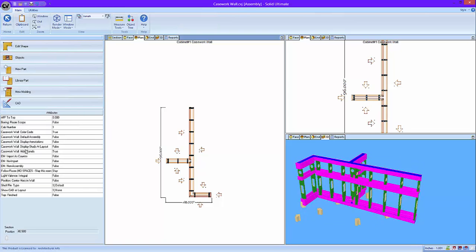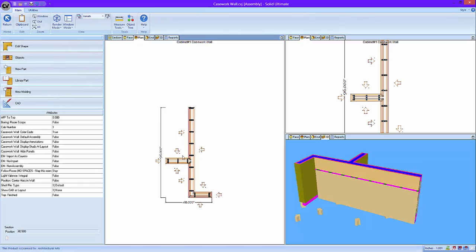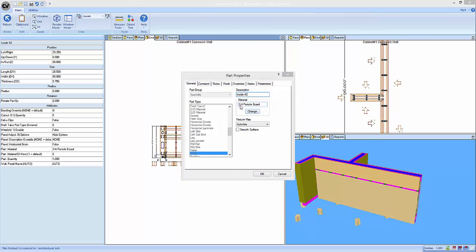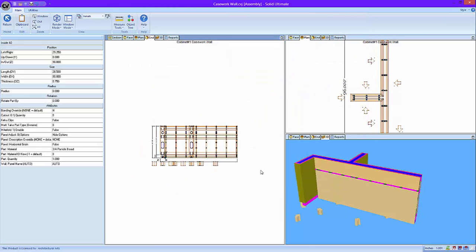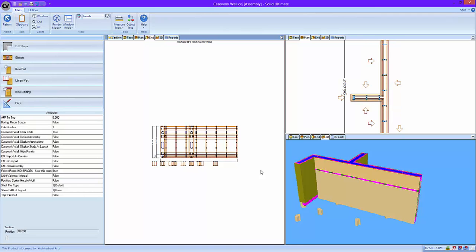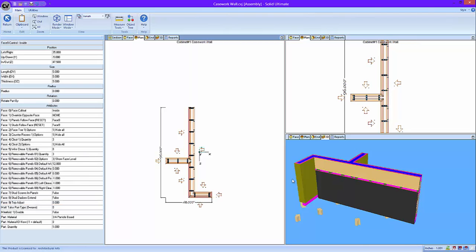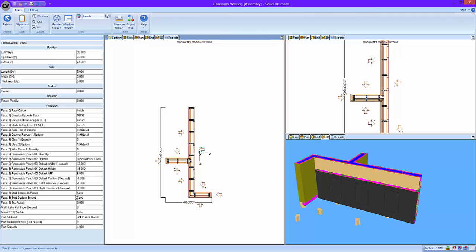Okay. Let's show our panels again. And then I readjust that inside one. Because I changed it earlier, I lost my black melamine override. We're going to come in here, click on this interface, and add some removable panel cutouts. Can't always get away with this, but we generally try to simply cut out using a small tool where our panels are going to be, and that way everything stays grain matched if it's veneer material. It's easy to do.